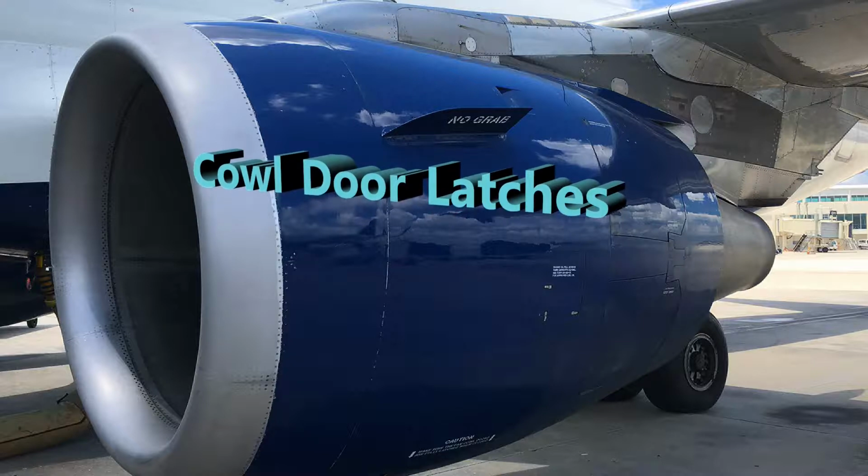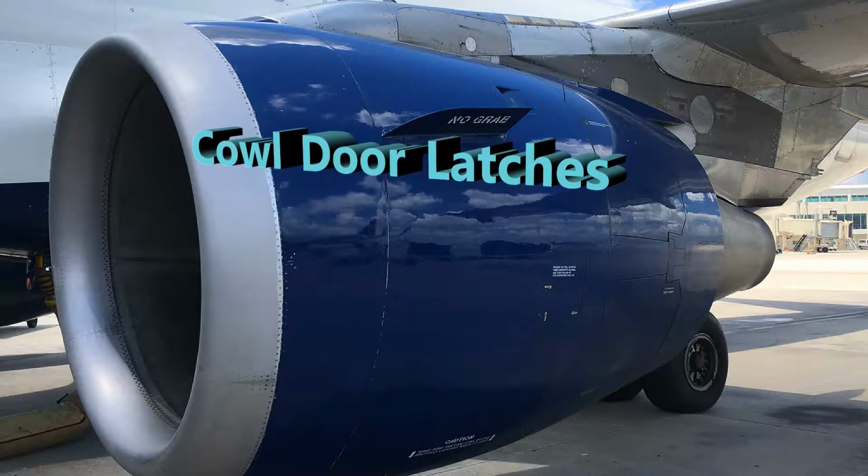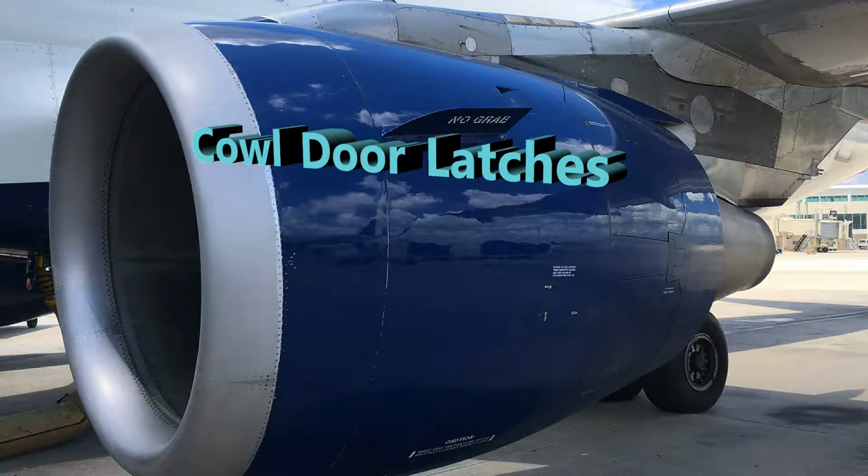But to open the fan cowls, you've got to get access through the access panel. So in order to release the latch access panel catches, you're going to do that by pressing the opening buttons. And then the second thing is you're going to open the 4 latches that hold the fan cowls closed. So there's 4 latches for the fan cowls. And then you're going to be pressing an up button to activate the power door opening system. And then when that's happening, just be careful, let it do its thing automatically. When it's finally reached its max angle,